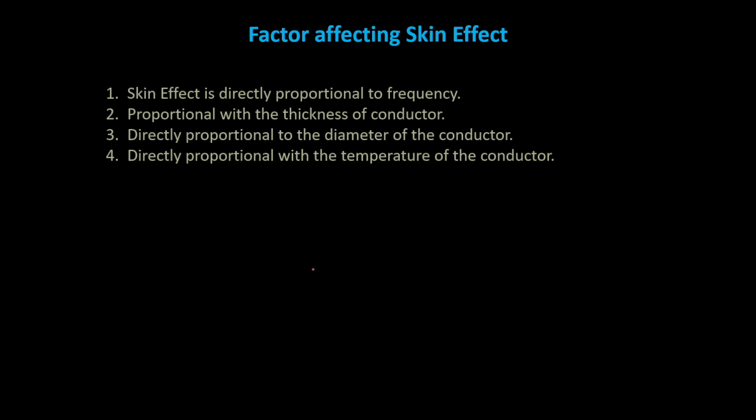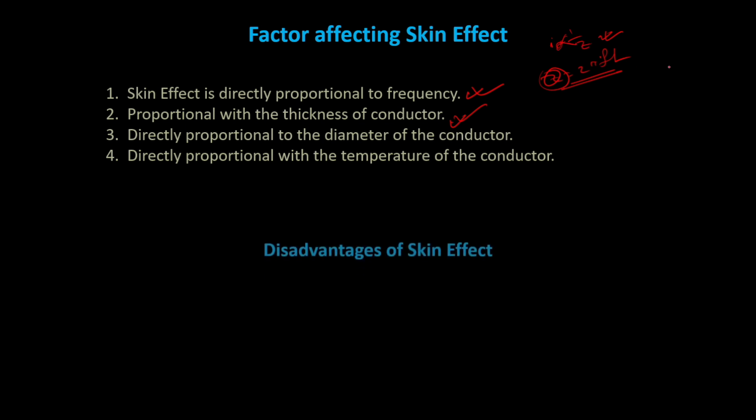And about the factors affecting skin effect, from those three equations we can directly say skin effect is directly proportional to frequency, because Z is equal to 2 pi FL, and I is proportional to 1 by Z, the same equation.